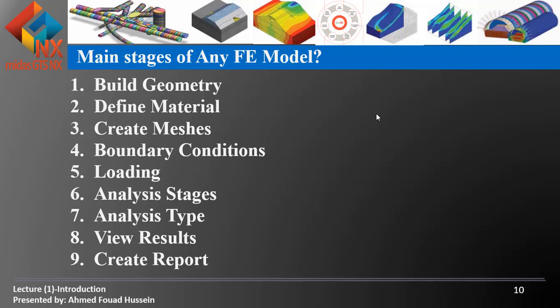After you create your geometry, you have to start to define your material. It depends on the material model you use. We are going to talk about these material models and the constitutive models in the following lectures, but you have to define the basic elastic and nonlinear parameters of the material you're going to use for concrete, steel, and soil, and it varies from one soil to another.